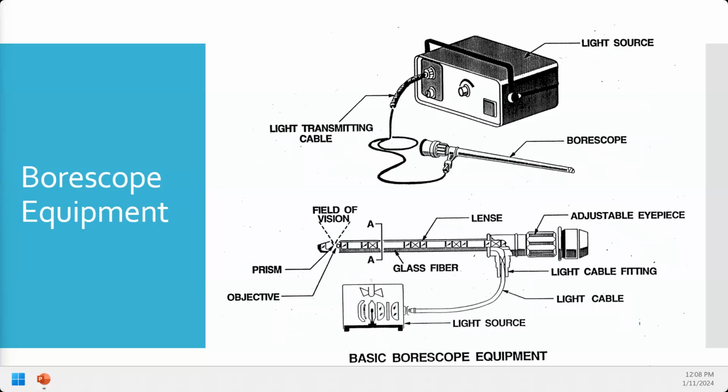It has to do with going into an area with potential for an explosive or combustible atmosphere, like inside a fuel tank or an oil containment of some kind. With the light source run through fiber optics, you're not going to risk sending electricity up to a bulb or producing heat with an old filament type bulb like in that little scope here, where the risk is probably pretty low, but you still are running electricity up here, and there still is a little filament in the end that's going to be hot and produce that light.